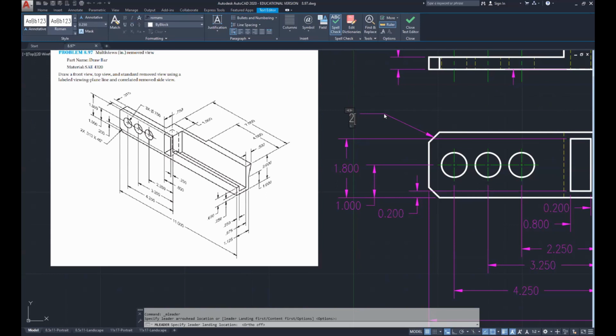To capital X space 0.313 space capital X .45 degrees. Add that little notation there. I'm going to do %%D, and that's going to add the degree symbol in there. A little bit of code for you.